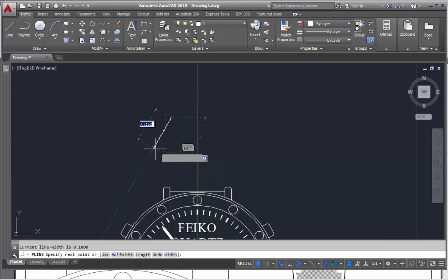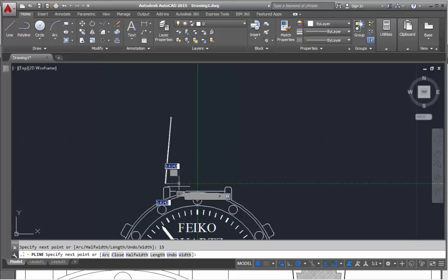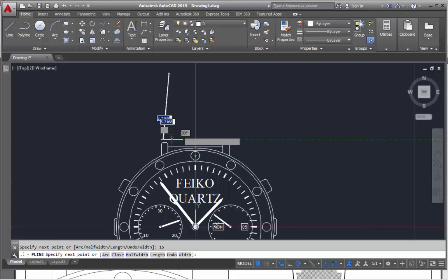And this time I'm going to do a different method. I'm going to use my tab key. I'm going to jump over to the angle and I'm going to set the angle for 95. And then I'm going to tab back. So this basically means I'm running up and down the 95-degree angle, and then I can enter 15 and then hit enter. So that's basically given me a 5-degree run in whichever direction I want to go.